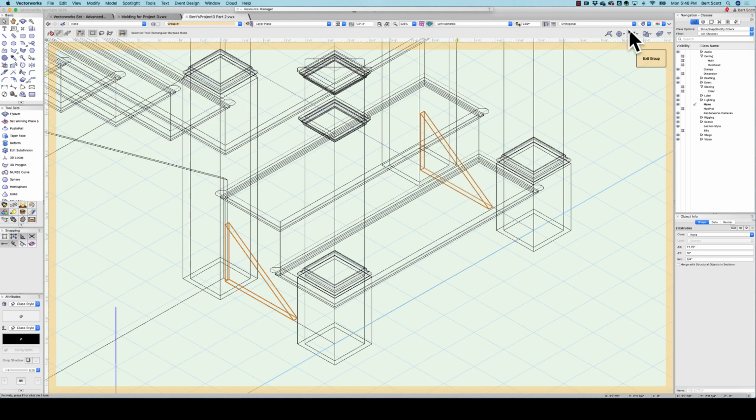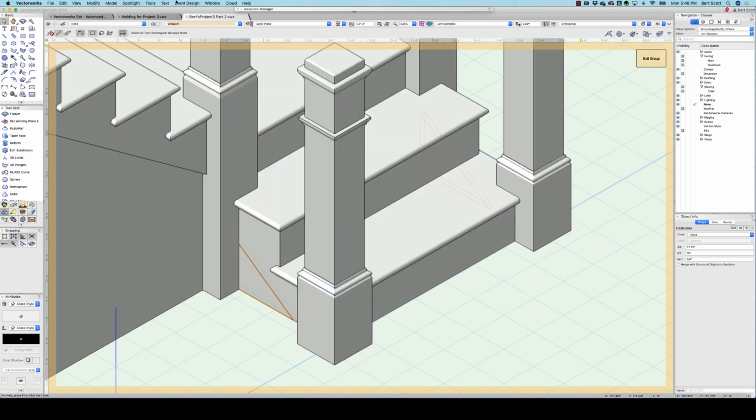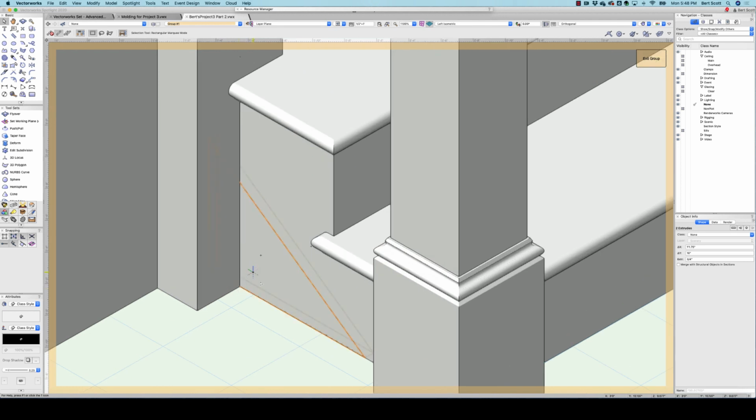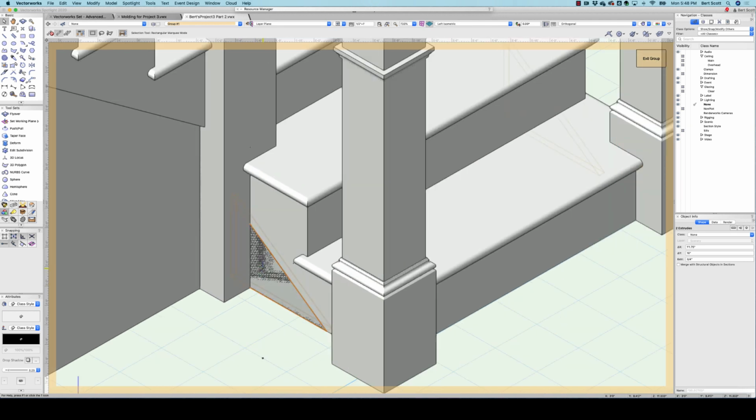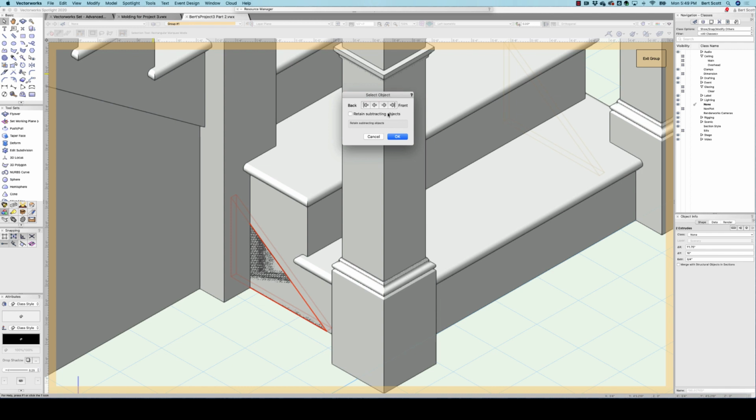actually, let's check and make sure that they're in the right place. Yeah, that seems correct. So sometimes that doesn't happen, but there it is, which indicates that I have two faces occupying the same space, which is good because I'm going to subtract one of them. So now model, subtract solids. I want to subtract from the big staircase.